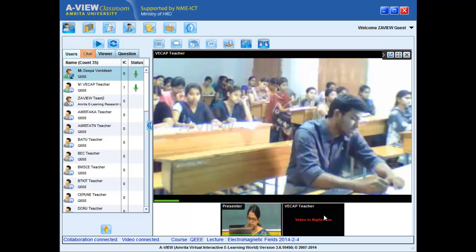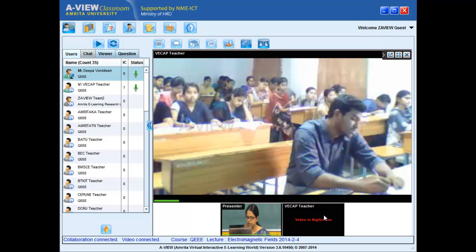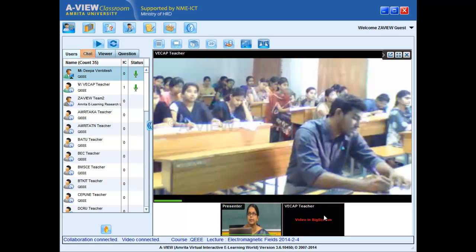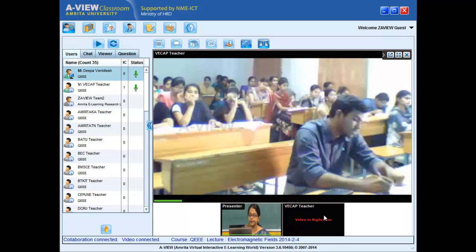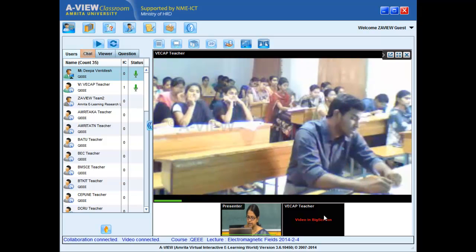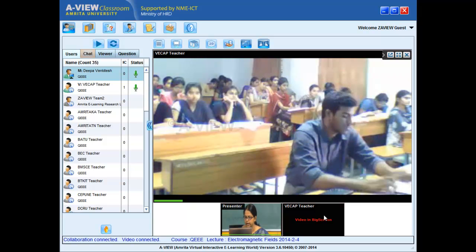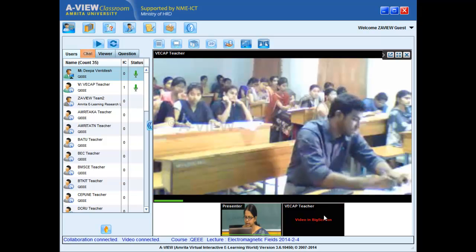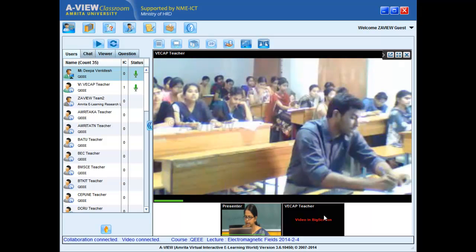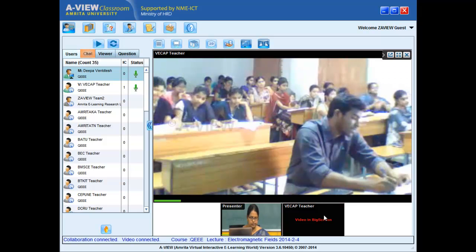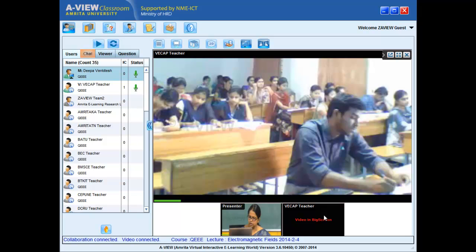In the limit, delta Z tends to 0. I know that this is the differential of I with respect to Z. Since I is a function of Z as well as t, I would write this as minus del I by del Z. And of course, as delta Z tends to 0, I can very well write this as C del V(z,t) by del t plus G V(z,t). So this is my second equation.